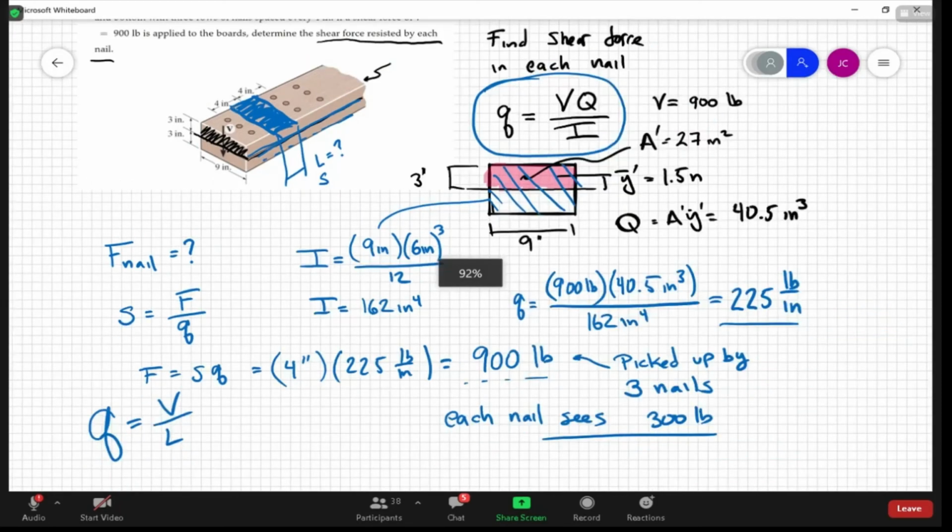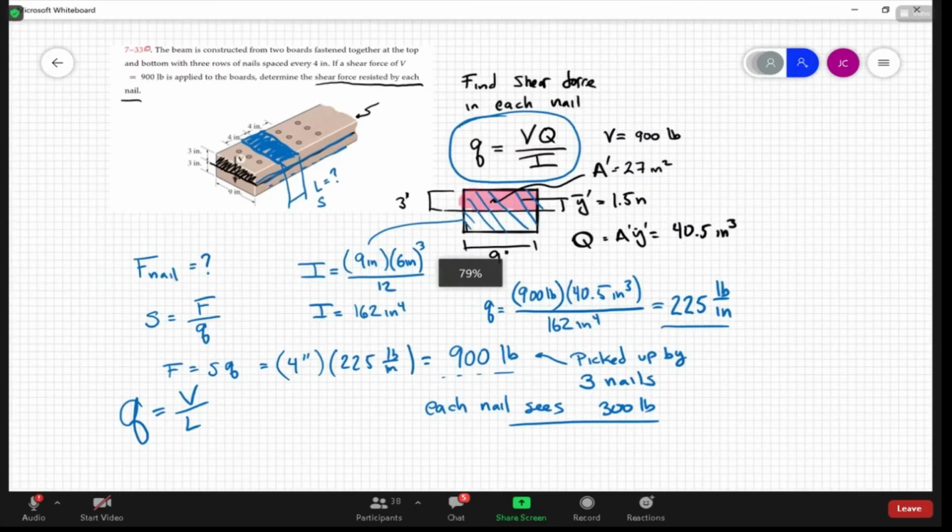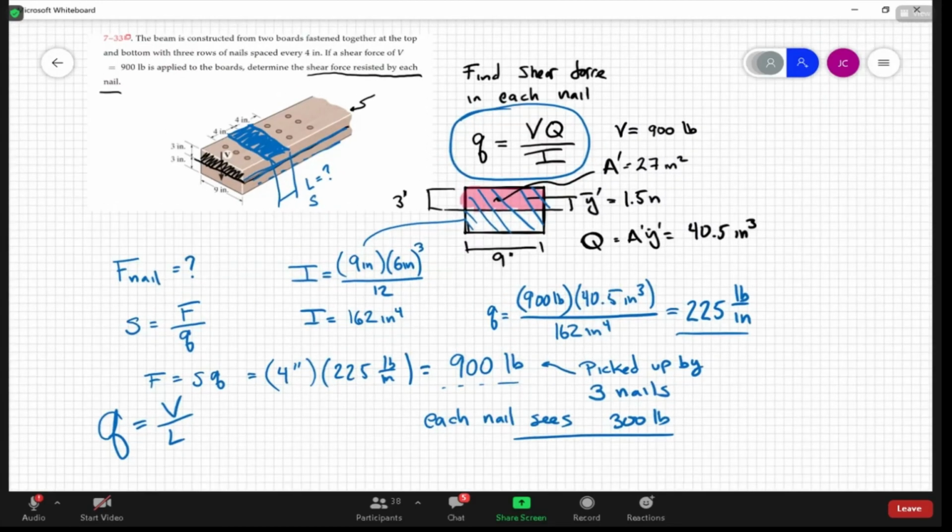And that's pretty much it for this chapter. So like I said, you understand how to calculate the transverse shear stress due to bending on a particular plane. You have to know what's the cross-sectional area that I'm going to use to calculate Q, what's the plane of interest, and then the area above that is the area used to calculate Q. And also you get the tau from that.